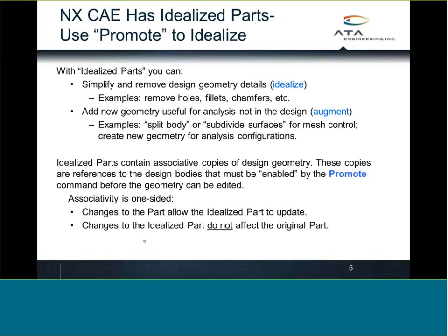trade studies. Now from a high level, the reason we do these operations in the Idealized part is because it's often convenient from an analysis perspective to do these kinds of operations on a solid body, clean up the geometry, make minor tweaks here and there for the sake of getting a nice high-quality mesh on the body. But in doing so, we don't want to corrupt the underlying design geometry because it's the part file that really conveys the design intent that the modeler had in mind when he or she created the part file.